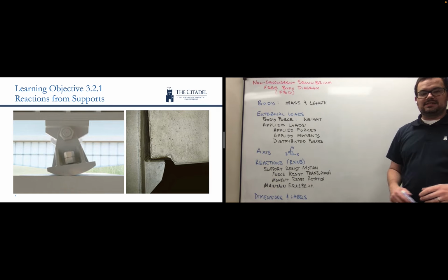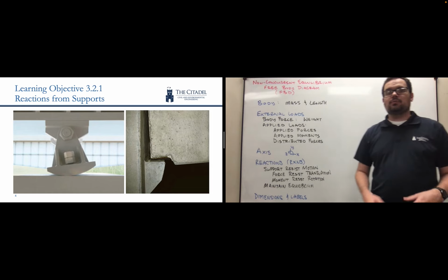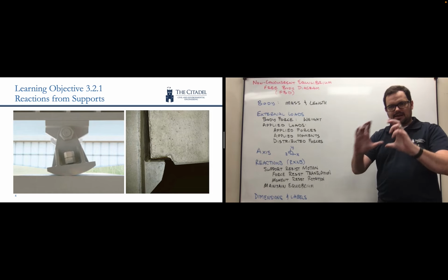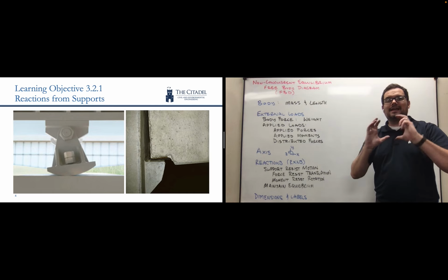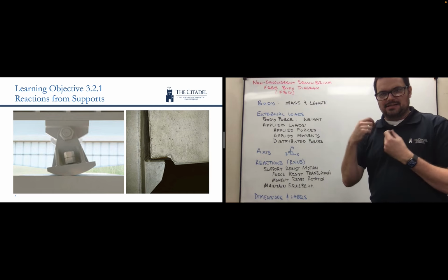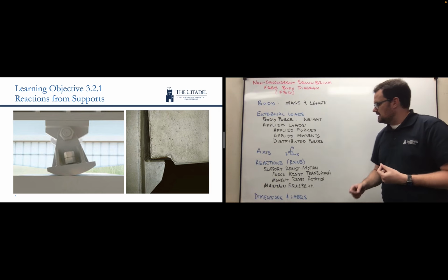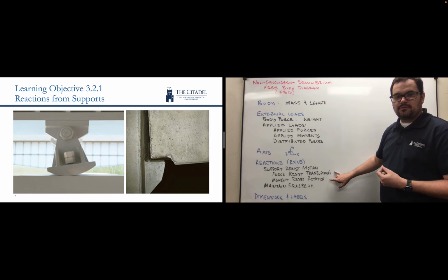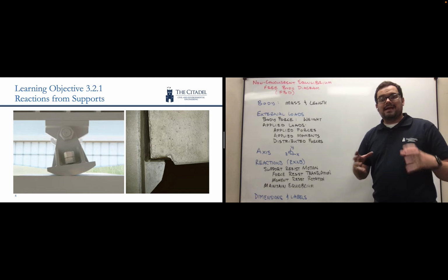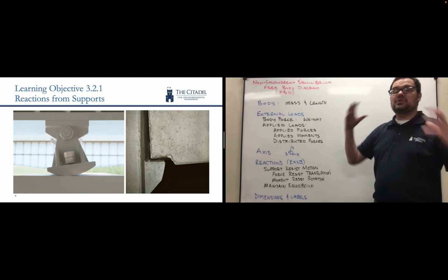The first thing we've got to acknowledge is that when we're looking at reactions, we're zooming in on the connection where it touches the ground, and we're thinking about how that reaction acts on the body. Our natural tendency is to say that clearly it's not moving, so it's going to resist all the forces and all the moments. But we have to recognize that that's for the overall system.